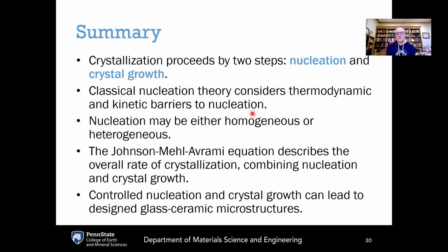We also developed Wilson-Frenkel theory for crystal growth rate, and combining the nucleation rate with the crystal growth rate at a constant temperature gives us the Johnson-Mehl-Avrami equation, which can be used to map out time temperature transformation diagrams. And if you have independent control of the nucleation and the crystal growth steps, that's what gives you the greatest control over your final microstructure. An example of that is these glass ceramics invented by Dr. Stookey.